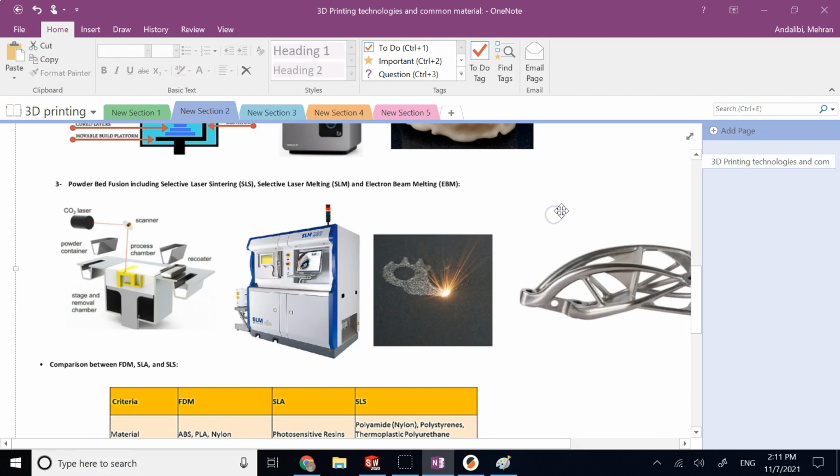But again, can I do every single metal that is in the market? No. For example, because they work with powders of metals, one of the things is some of these machines have a hard problem with aluminum, because the powder of aluminum can easily be set on fire. It's very volatile, and some of them are working very well with stainless steel, some of them even with titanium. But they're increasing the range of metals that they can print.